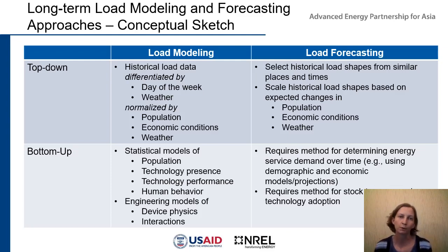If we're doing bottom-up load modeling, then we're trying to develop a more built-up, statistically representative, physically accurate picture of how energy demand actually appears, maybe starting at that household or that building level, and then adding up a bunch of those to create an overall picture of load.